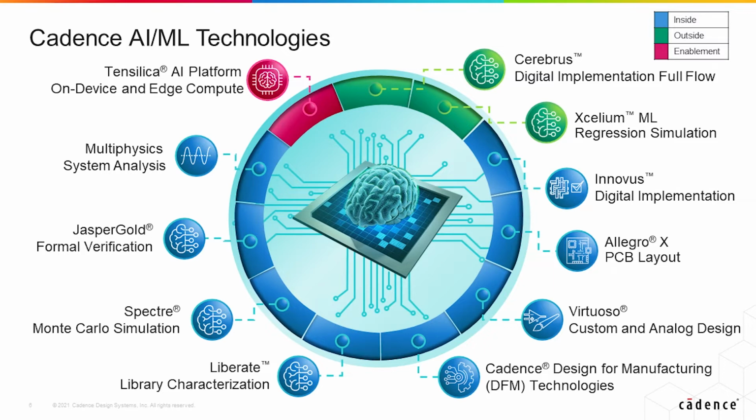And finally, the Cadence DFM technologies. Design for manufacturing is an important sign-off step in advanced nodes. To facilitate DFM sign-off, machine learning prediction capabilities have been added to the Cadence Litho Physical Analyzer to effectively catch more yield-limiting hotspots and repair previously undetected hotspot patterns. It delivers up to 33% greater detection efficiency versus traditional pattern matching checks with less than 10% runtime impact.